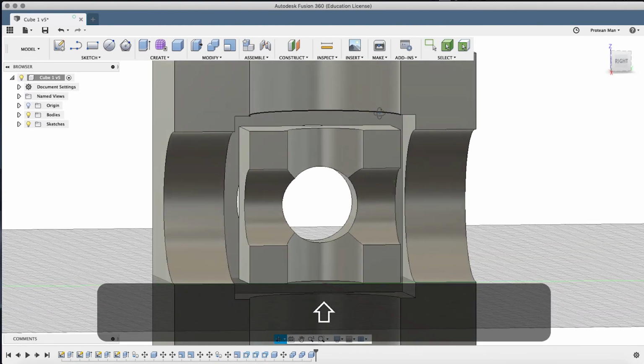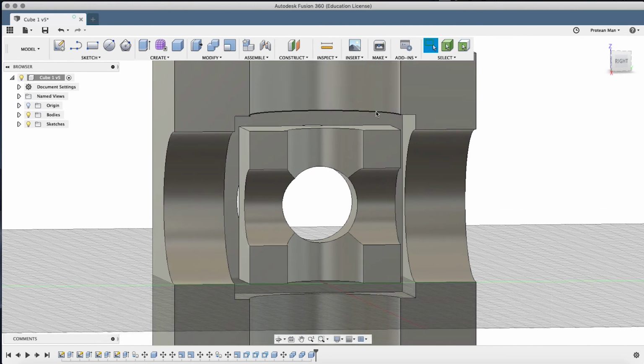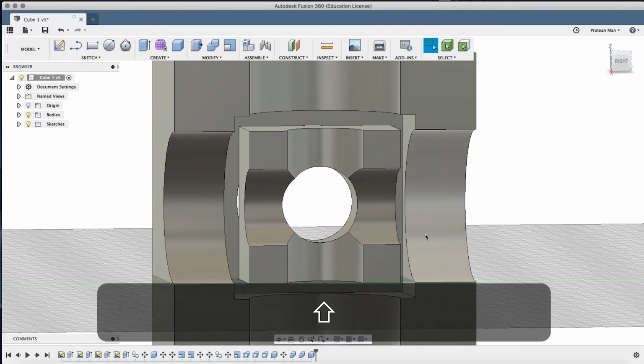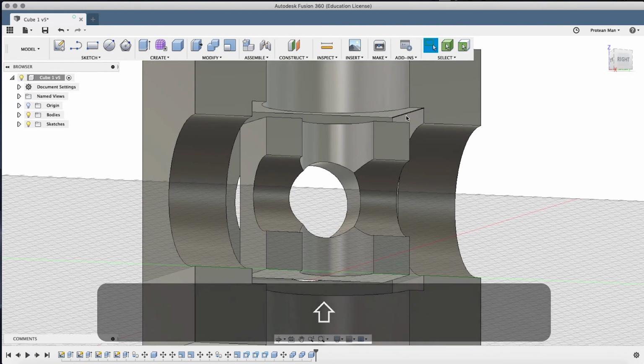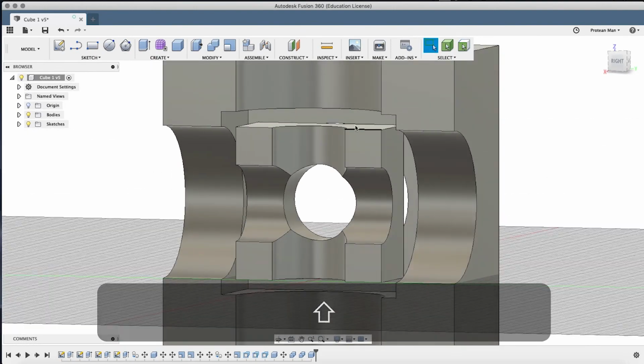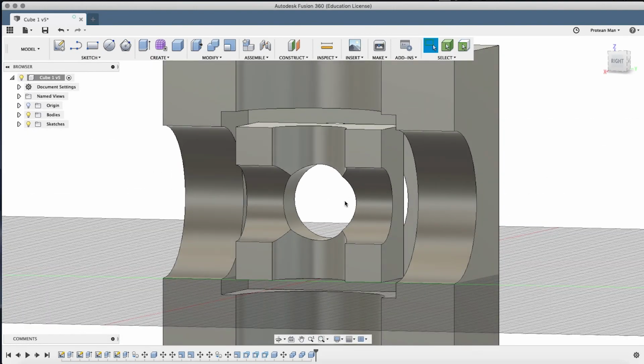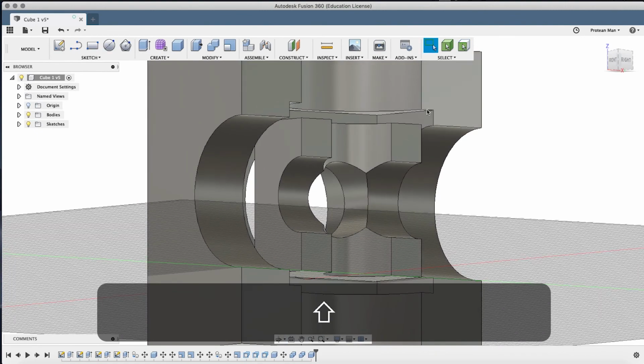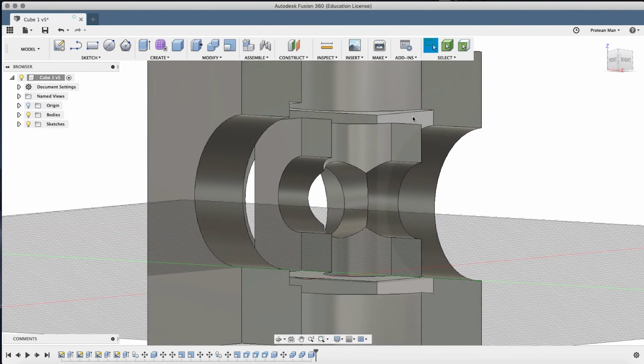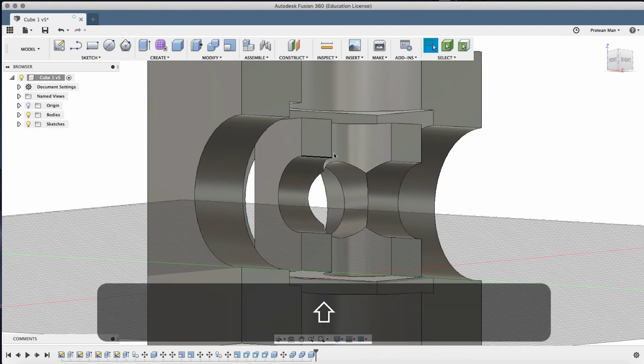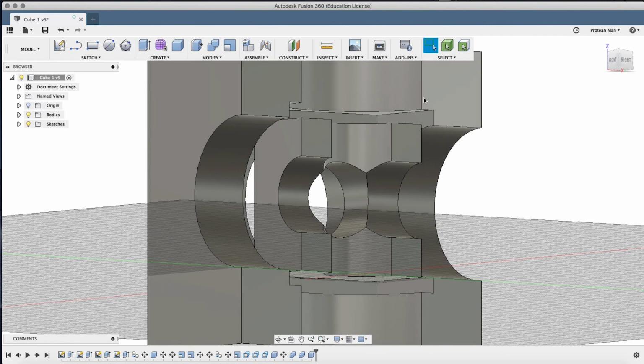We made 3 cubes, and when one was removed from the other one, we used that cube as a cut function. And what happened was, look, you see this gap here, this inside shape of a cube is now separated from the center cube. And this is adding a buffer zone so that if you want to print this object, it will be a cube inside a cube that can move if you print it properly, but you can't remove it from the actual outside cube because it's one solid object.